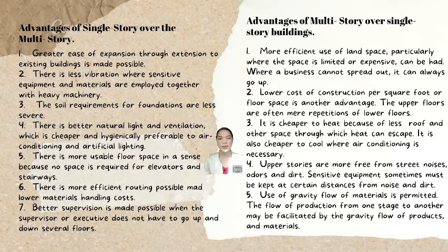First, greater ease of expansion through additions to existing buildings is made possible. Second, there is less vibration where sensitive equipment and materials are employed together with heavy machinery. Third, the soil requirements of foundations are less severe. Fourth, there is better natural light and ventilation, which is cheaper and hygienically preferable to air conditioning and artificial lighting.